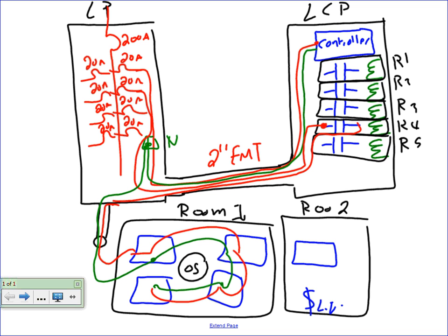I brought the hot, and I broke the hot through a contactor. Can you see where the hot landed? Can you guys give thumbs up, say, Chad, yeah, we know where the contactor landed? Yep. So you brought the hot only, not the neutral. In the panel, you broke the hot, and you brought it back so you can join the neutral to go all the way to the lighting panel, to the lights. Thumbs up, yes, we understand it. So that's what we call the power circuit.